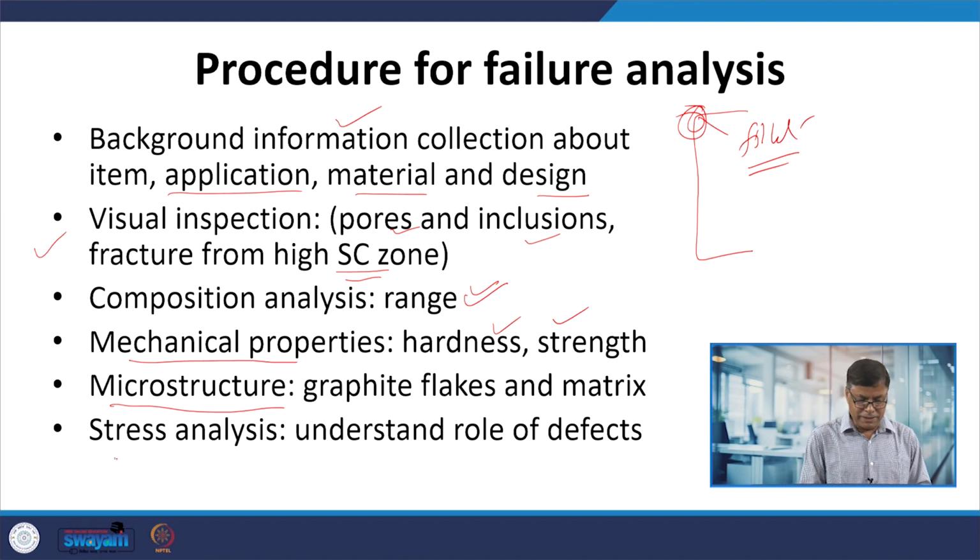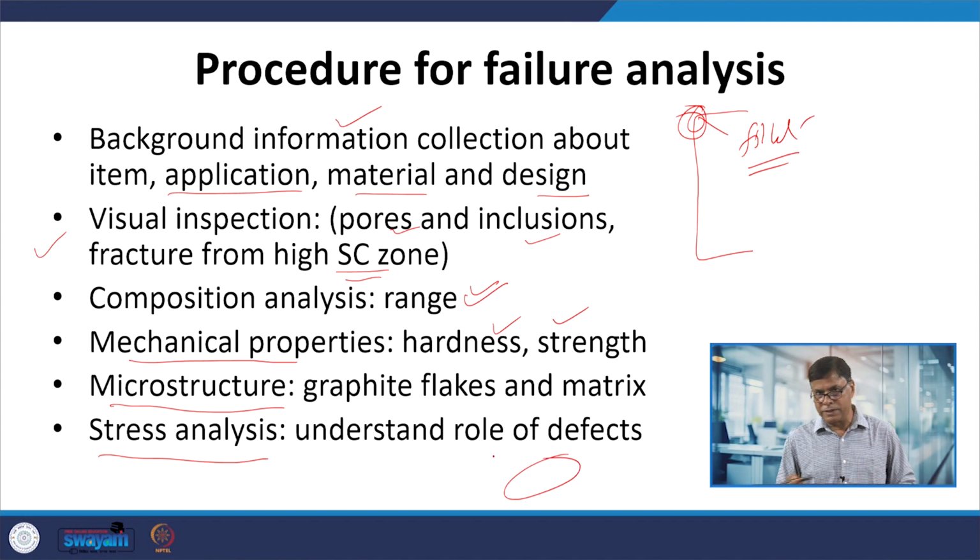And also a stress analysis is needed to understand how far the presence of defects, if they are there in the cast components, can contribute towards the failure. So, this is done considering the defect size, the reduction in the load resisting cross sectional area, and the kind of stresses that can occur due to the presence of this defect or stress concentration factor.